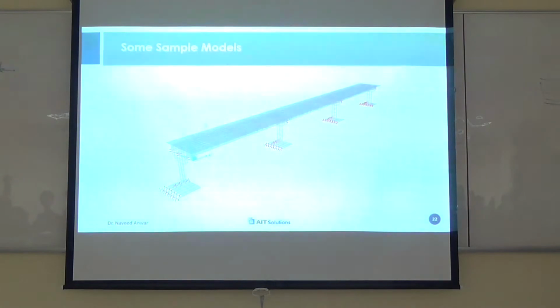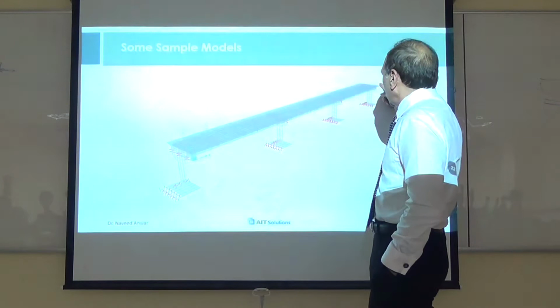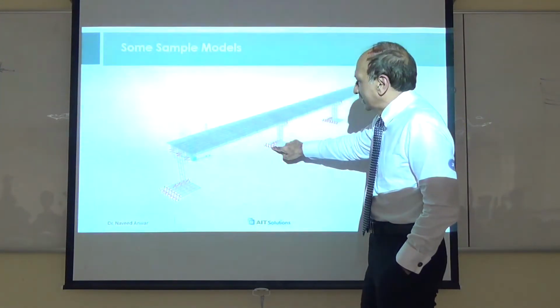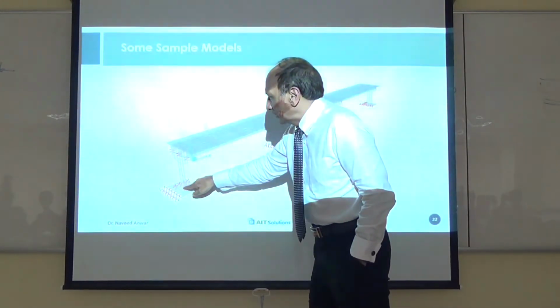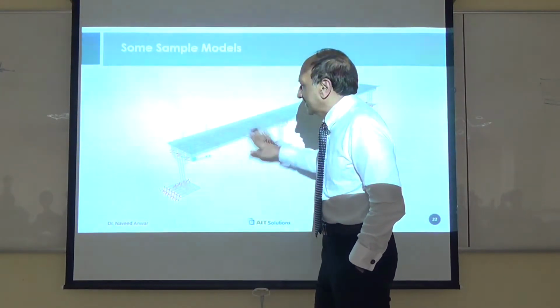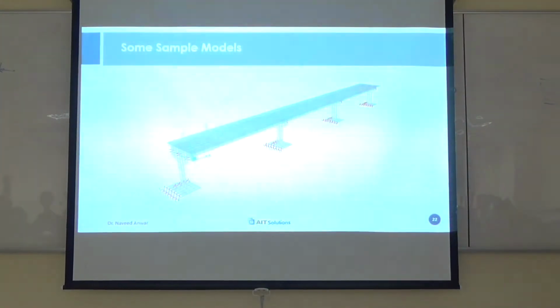So this is another sample model. So now you can see from here that this is a 3-span, so not only one span, but 3 spans: bearings, soil. These springs you can see as soil, vertical soil, horizontal soil, bearings, girders, diaphragms, deck slab, piers, pier heads, everything is complete for 3 spans. After the expansion joint, another will start. Right? So you can extend that basic concept to 1 span or multiple spans. Important is that you model all the elements in the bridge as accurately as possible.